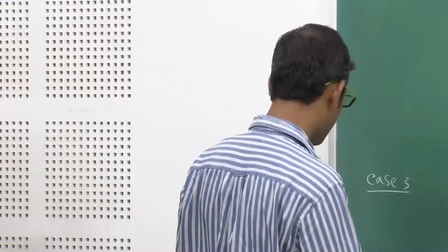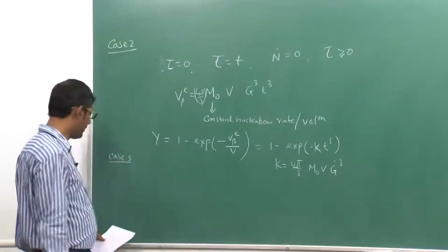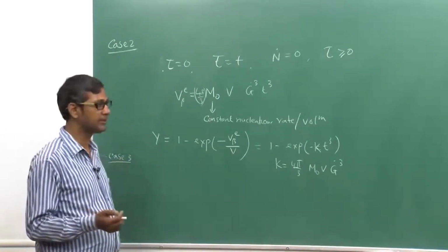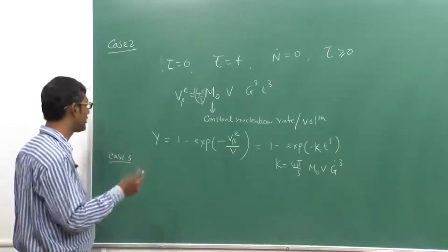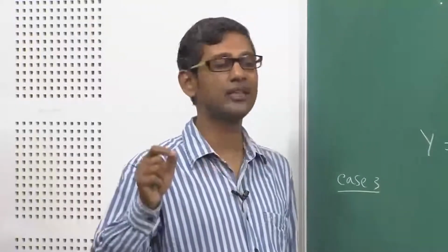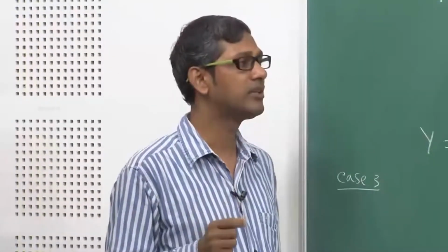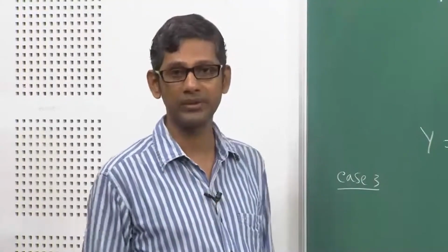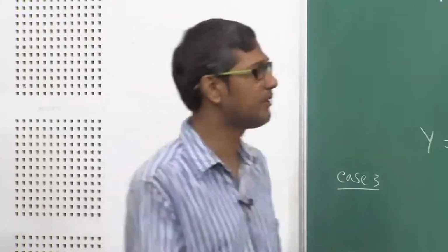So in these cases, when the grain boundary nucleation is exhausted, then growth will happen only. When the growth takes place from the nuclei along the grain boundaries, it will happen along the direction perpendicular to the grain boundary. That is obvious.